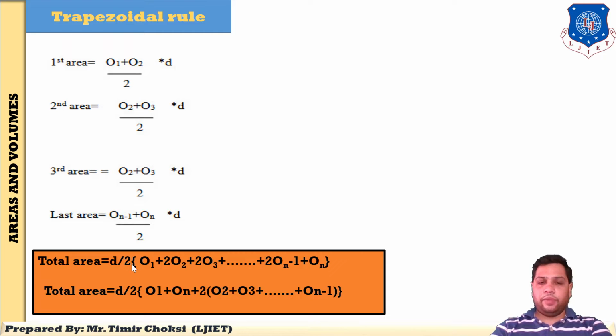It is easy. D by 2, common distance divided by 2. Here O1 and On are not multiplied by 2, so I have taken them separately: O1 plus On, and all the other ordinates are multiplied by 2. So 2 is common, and O2 plus O3 up to On minus 1.